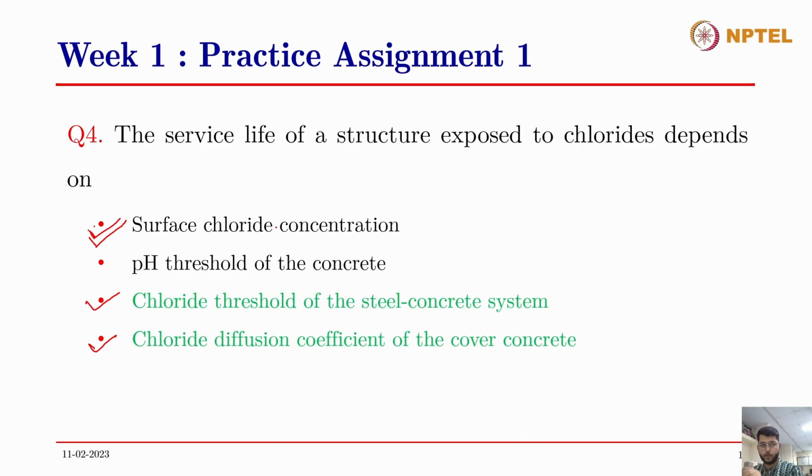But anyway, what I want to mention is that once the chlorides get inside the concrete matrix, they get accumulated on certain rebar locations. But corrosion will not take place until the depassivating film is broken, and that is related to the chloride threshold.